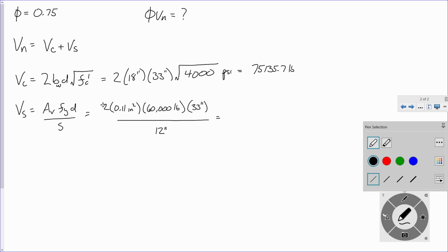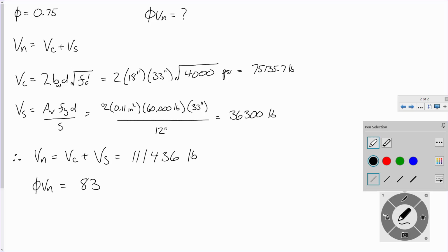Plug and chug, and that gives you about 36,300. So therefore, Vn is Vc plus Vs, which is 111,436, and phi Vn is 83,577 pounds.